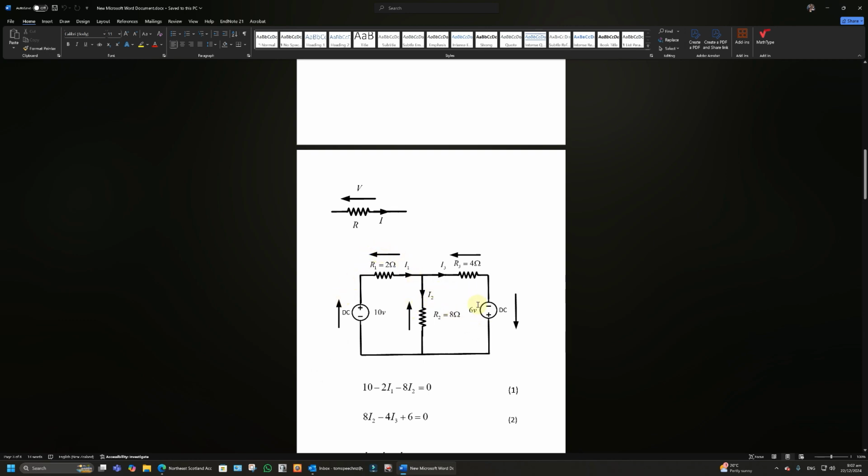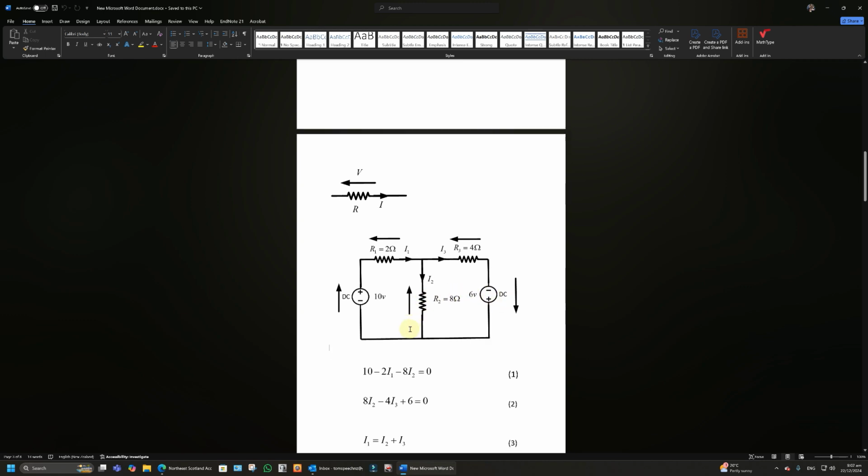Now this one's perhaps more difficult to see, because you normally think of simple circuits, if you're at school or something, with the voltage on the left hand side. So it's on the right hand side and it's going the other polarity, so that confuses people. But here we'll take that to be positive just like this one, so that's going to be I2 R2 or 8I2. And then this one, because it's head to head again, it's going to be minus I3 R3 or minus 4I3.